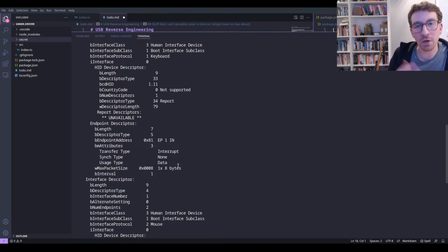There's also something called a bulk endpoint. In a bulk endpoint, you are sending quite a lot of data, but you're not sending it constantly. You're not streaming video with this. It's more like you have a mass storage device and you're pulling files off it. You send each chunk of data to the operating system in a big bulk package.